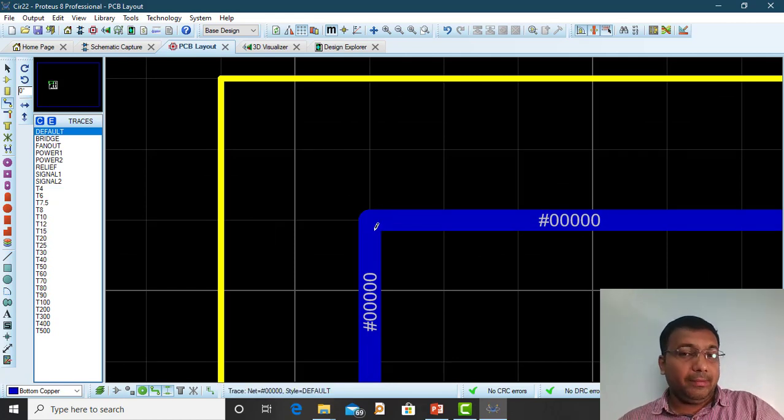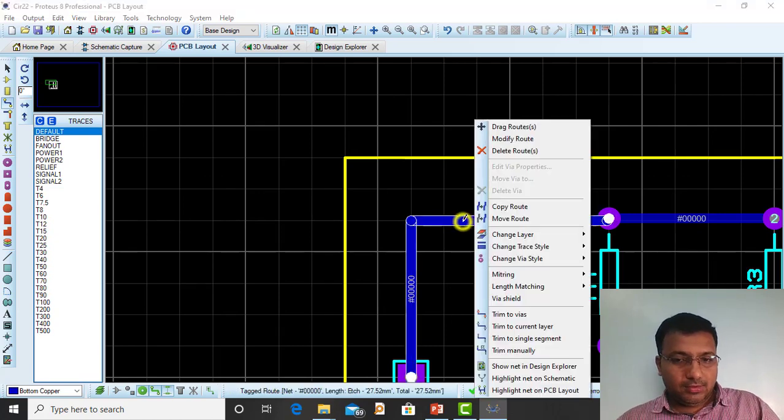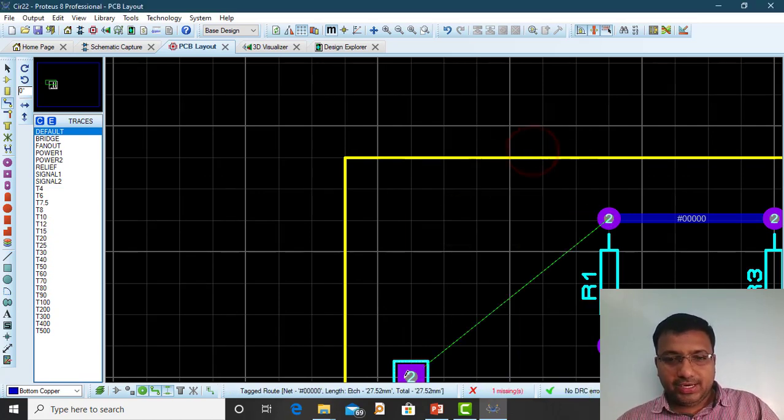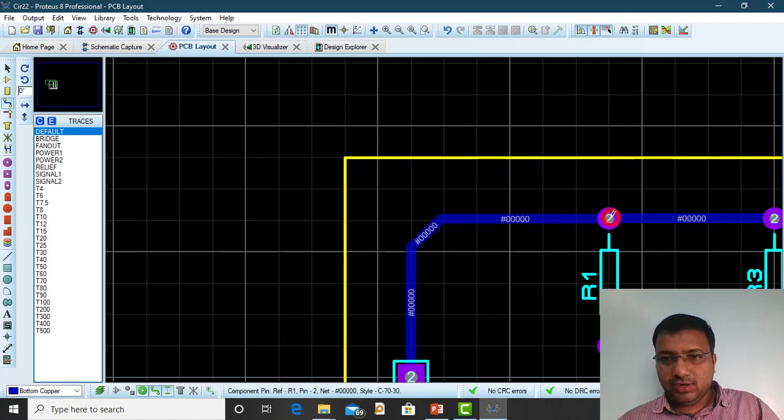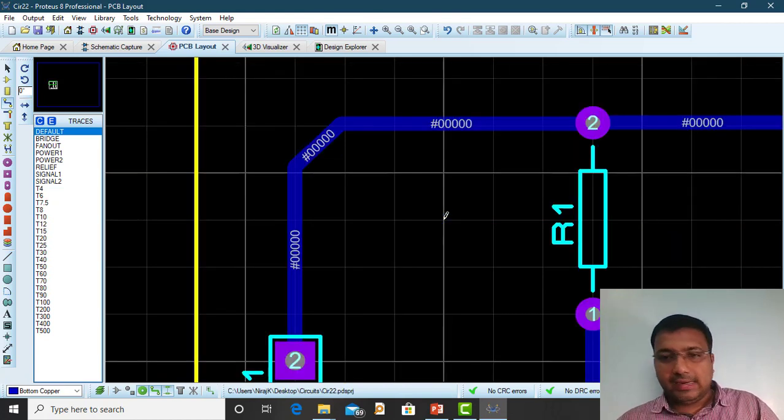Because of this the copper may detach from the epoxy layer, so the life of the PCB will reduce. So every time, don't make 90° turns at the edges. We can have a tilted edge, and then we need to connect it. So always avoid 90° connections at the edges. This is the rule while designing any PCB.